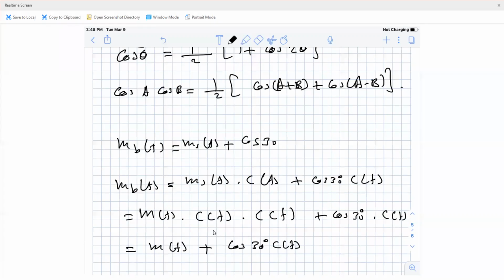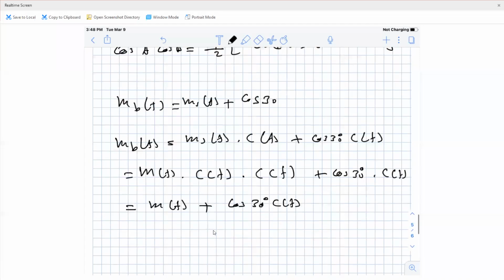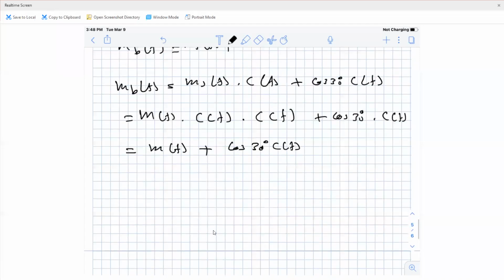Again, if we go to the receiver of the direct sequence spread spectrum, at the end of the receiver we have a matched filter and a threshold. Matched filter and threshold means we are looking at an integrator and a threshold. Integration means finding the sum of the areas. Now, going back to C of T, we said that C of T consists of 0, 1, 1, 0, 1, 0, 0, 1.